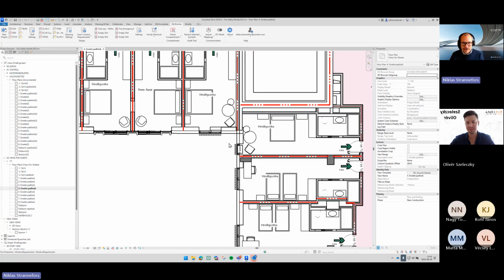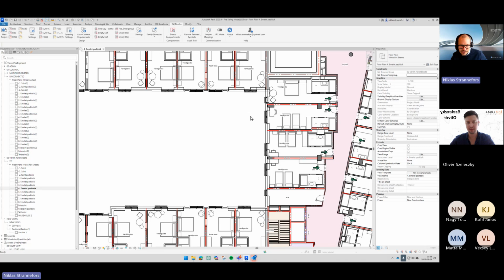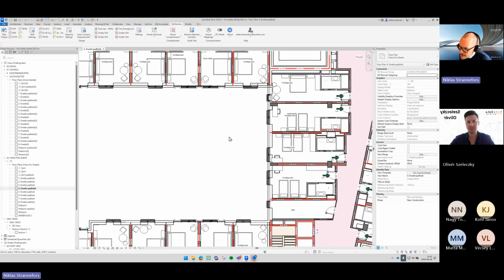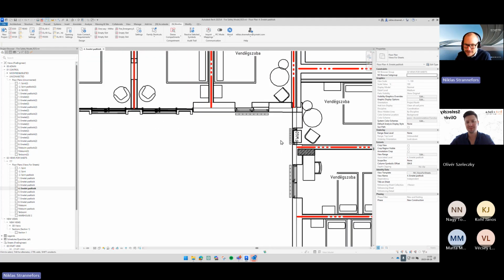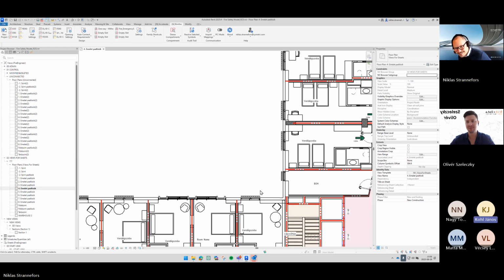That was the only window that is definitely shorter than 2 meters between each other. Diagonal. It's the same in Hungary. Like in Sweden, if you have a corner like this and there are 2 meters, one of those needs to be fire rated. It's a bit complicated, but simplifying, it's 2 meters, and that was the only one. You should measure it, but I'm lazy. It depends on the angle and if it's openable. We have it a bit simpler because we have diagonal 2 meters, depending on the wall, and 1.2 meters in height. So if it's closer, there's a risk of external fire spread.